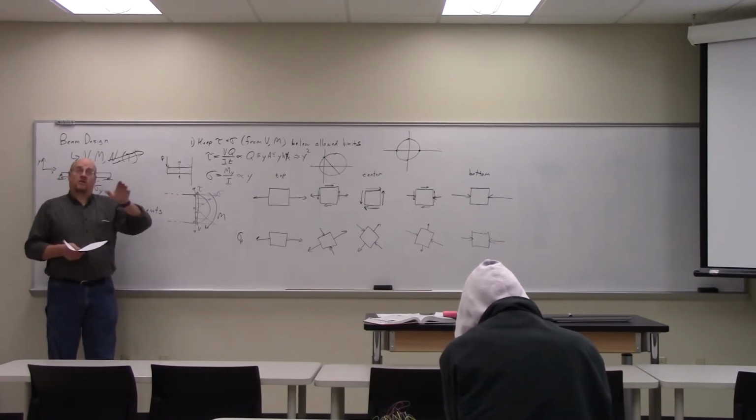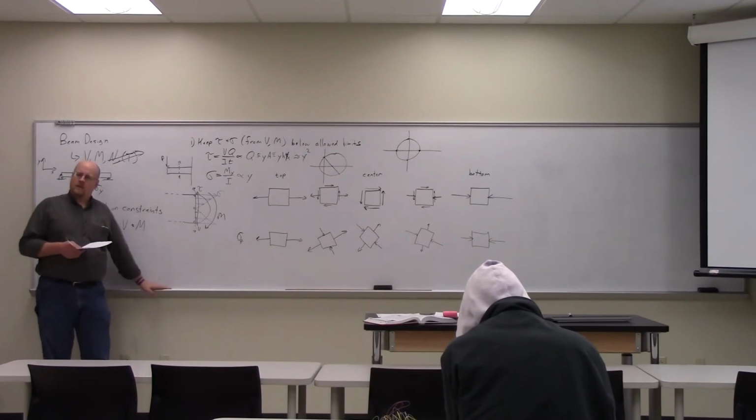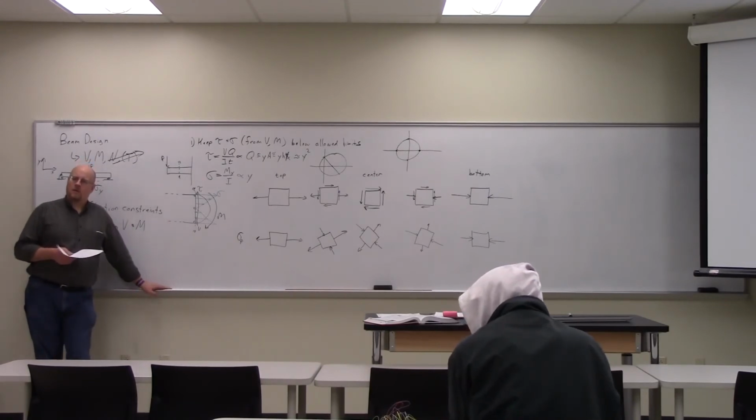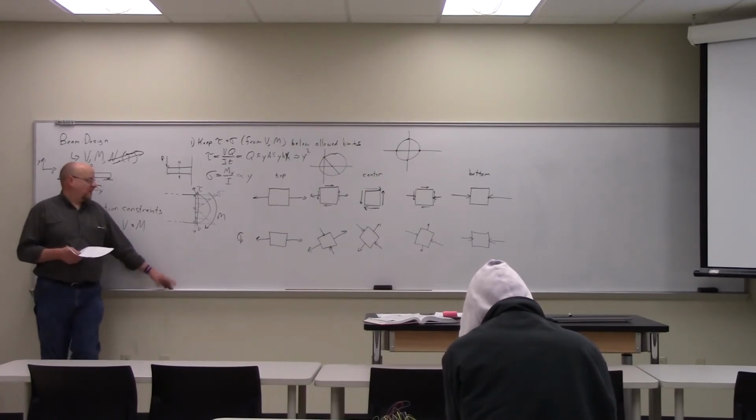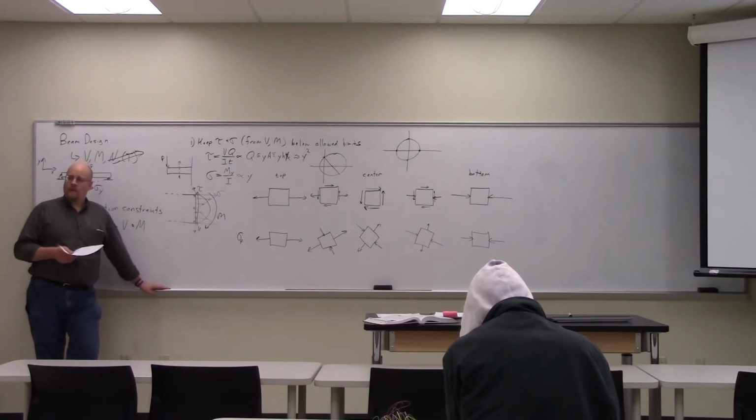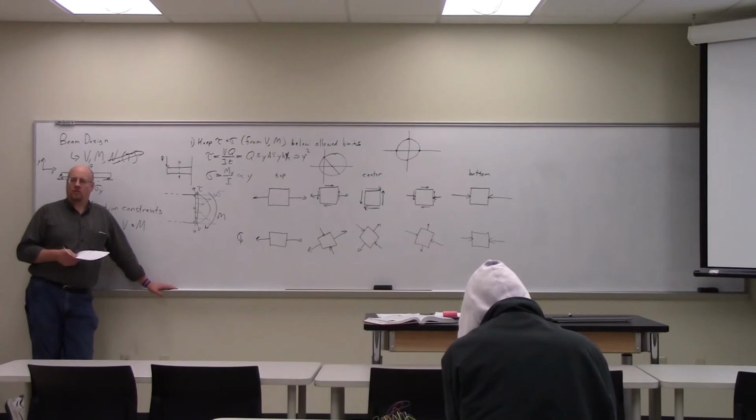I'm sorry, tau xy versus tau xz. Doesn't it come down like this and then come back up for an I-beam? Like you'd have that for tau. You're applying tau across the I-beam. For the middle section, it looks just like that. But it doesn't go to zero at the edges. The web doesn't go to zero. At the top and bottom of the web, the shear stress is not zero. Oh, yeah, I guess.